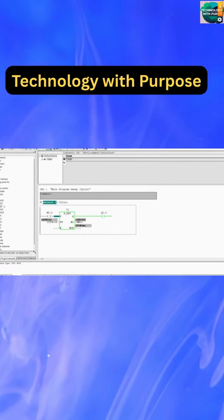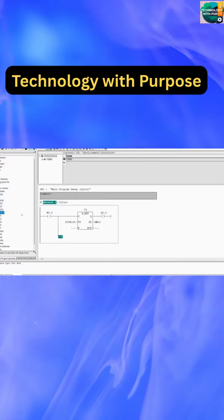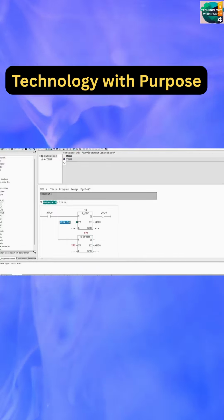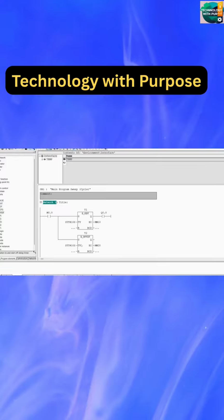Now let's study the off delay timer also. Let's take the off delay timer from the left tree. Now I'm going to use the same trigger M0.0 to switch on the timer, also use the same 10 seconds as preset value and MW20 as BI. Let's also name this timer as T2.